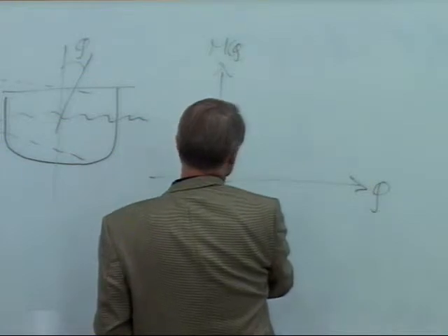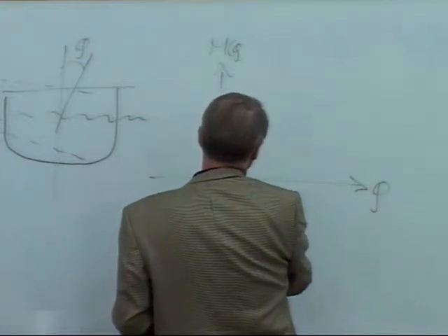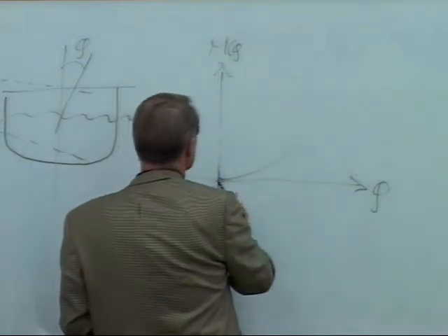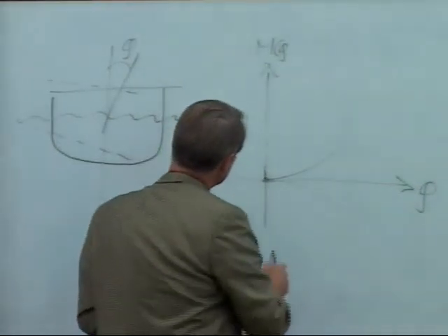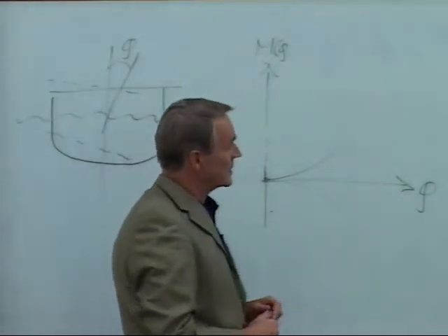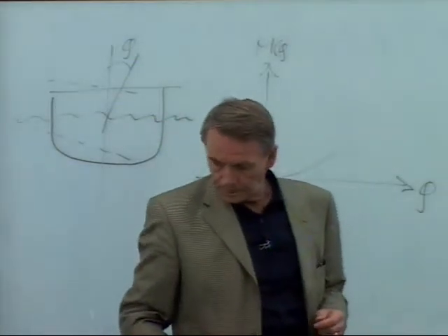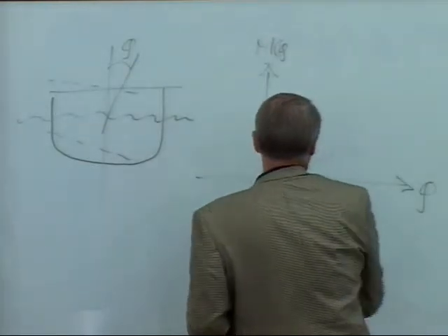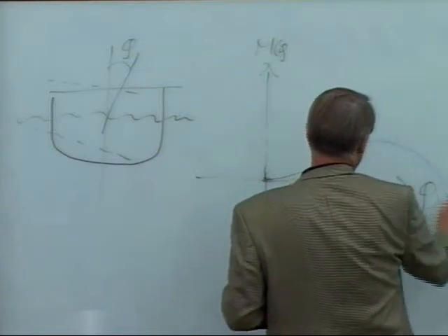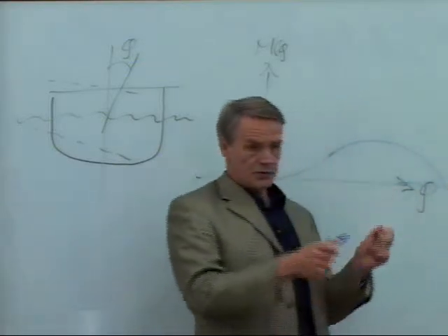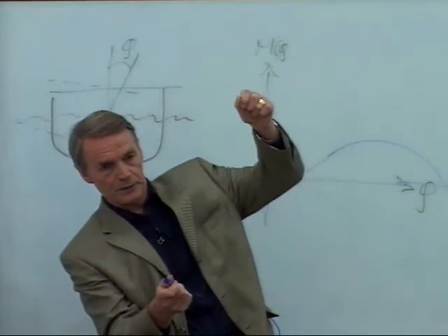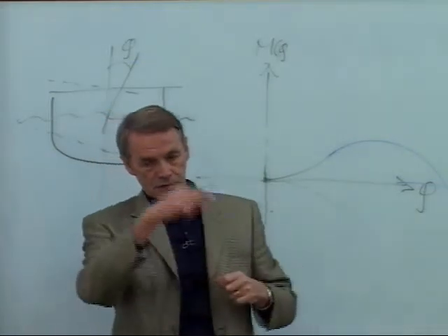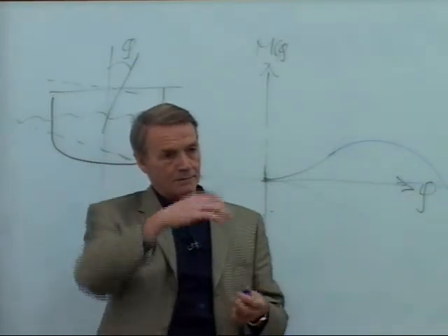Of course, the moment as such starts at 0, and then it will normally go up, but it can also go down, right? But if it's negative, of course, then it is unstable. But the function can go something like this if we have very large rotations. That means if you take a boat and you tip it over, you use larger and larger force, but then you come to a point where it actually will just tilt around and then bottoms up.